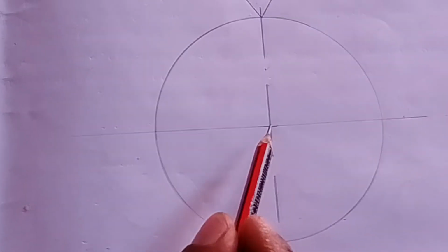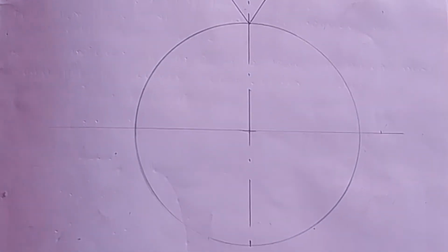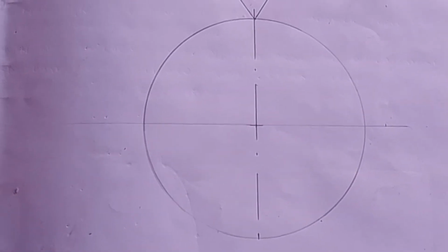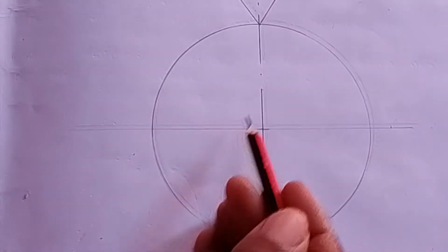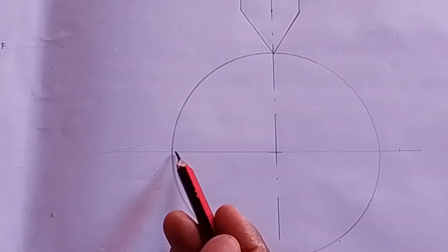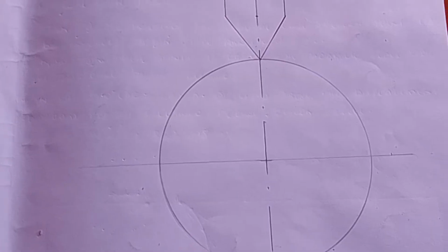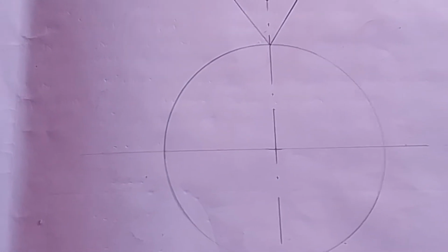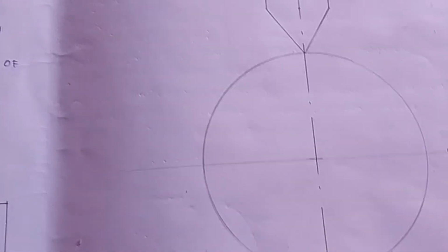So from this center line here, you will divide the outstroke. You will identify the 60 degrees of the outstroke, then measure the dwell, then measure the return stroke according to the rotation that you have been given. In this, we have not been given whether it's clockwise or anti-clockwise. In the question, you have not been told, but I just use a clockwise rotation.